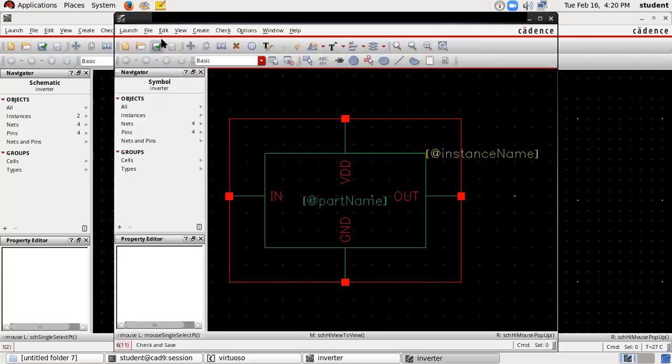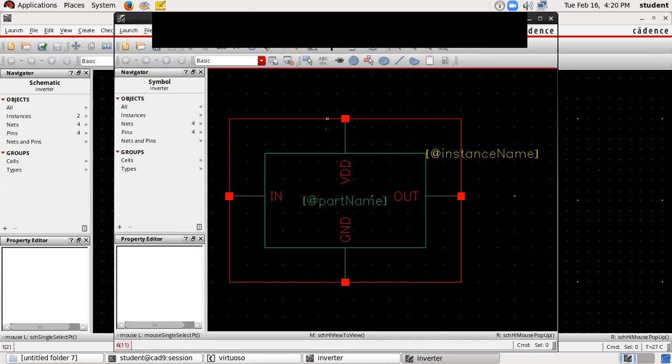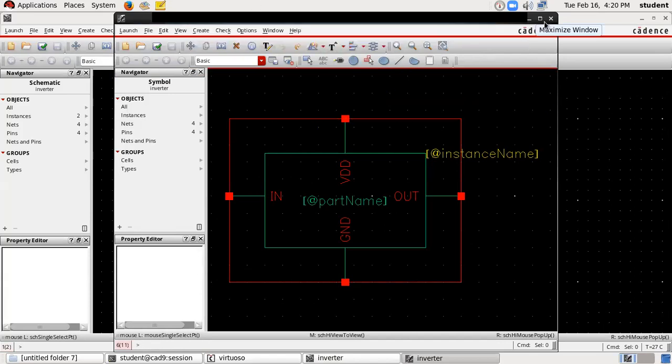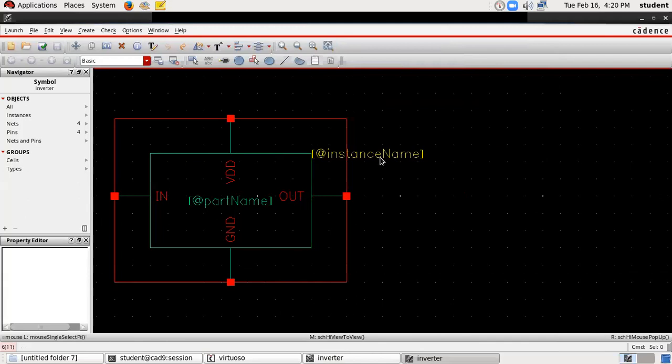As you do it, it opens another window. This is the layout tool for Cadence, where you can work with different layouts and design layouts for yourself. This is the layout it is creating for me. My inverter is going to look like a rectangle if I place this, but I want it to look like a triangle, so you can change the shape.